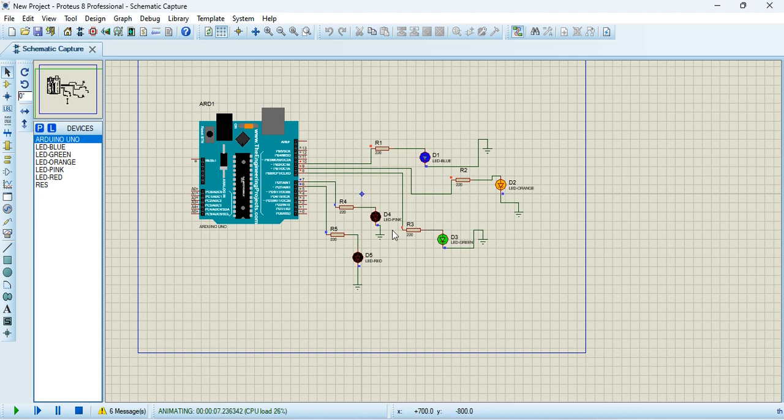Everything we can do with that code by giving a delay operation in the middle of the high and low of the LEDs. So after some time the LEDs will turn off and turn on, like that. Simultaneously the operation will go on. It's still running. See here, this is a stop button to stop the simulation. Until I press this button, the loop will go on. Now the 8th pin LED is turned off.